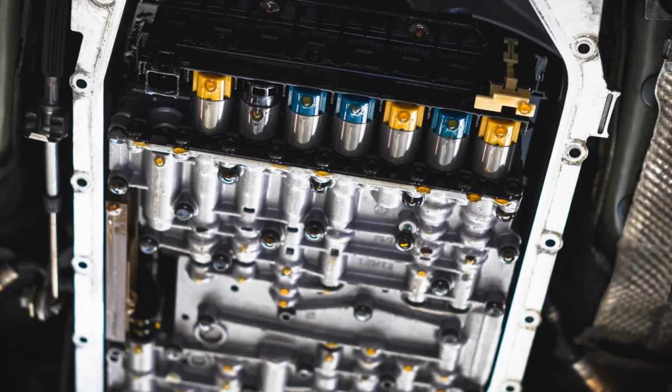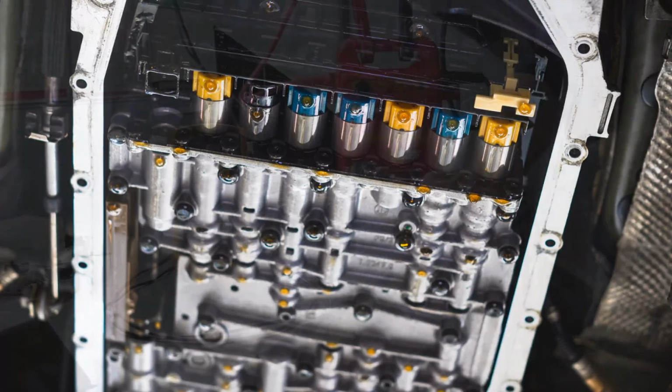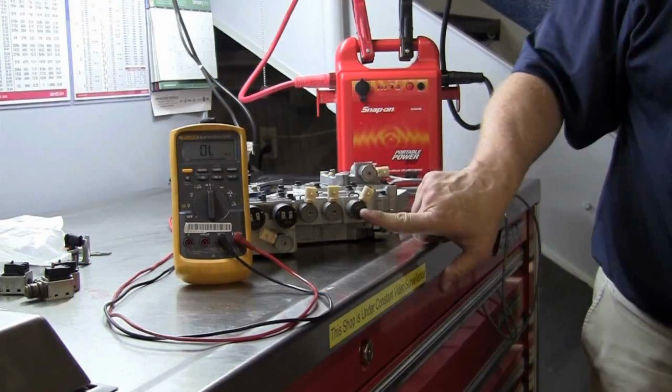The plunger can become clogged with chips from worn parts and lubricating oil. At first there are difficulties with shifting, the solenoid starts to wedge. The amount of carbon deposits gradually increases, leading to valve and bushing failures. It is important to keep in mind that even the most reliable solenoids fail sooner or later.